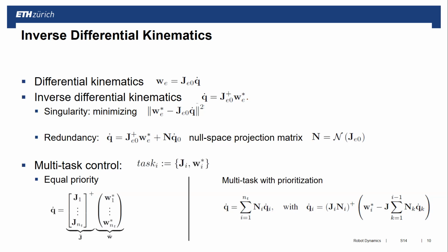Because the same then also came up later when we looked at inverse dynamics. So make a mental note here. We wanted to solve the inverse problem of that. We went through pseudo inversion, which is equal to least square optimization, to this set of tasks, and then we showed how we can use this and solve this with a QP that has different priorities.